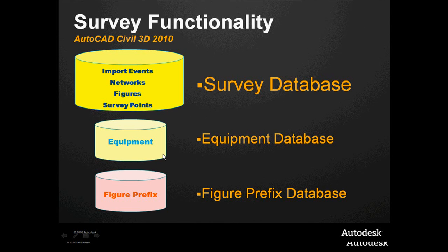There is the equipment database. What that does for us is it will maintain specific information about our equipment. So if I have 4 identical Trimble units, each one may have slightly different calibration information or standard deviation, prism constants, different things that even though they're all identical equipment, they all have slightly different aspects. And if we're going to create a least squares adjustment and we want the highest level accuracy possible, some of those factors may need to be adjusted into the equation.